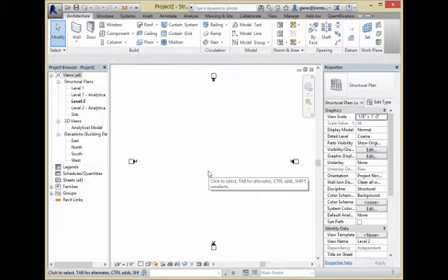Okay, what I'm going to do is start creating a little frame structure, and just to give you an idea of what I'm trying to create. In most buildings, I'm just going to make it a very simple little rectangular building like this right now. I have a little structure, and within that structure, to support that roof, things may be supported by the outside walls, but very commonly we'll have some columns in here that are coming up from the ground. In a structure like this, there might be 6 of them. And then between those columns, we're going to have some beams that are supporting things.